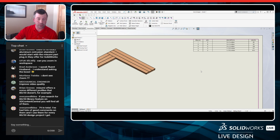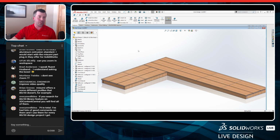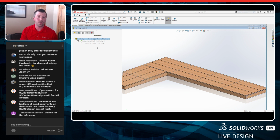Now, I want to point out one last thing here, and then I'll show you our final design in a trimmed room, is as you're working in here inside of the Weldments tool, you may notice that the Weldments configurations has 2 derived configurations that's created when you enable that weldment option. One is the as machined and one is as welded.